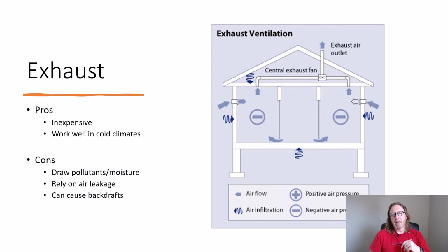Also, you have to realize stack effect naturally moves air in this same manner. So even if this exhaust wasn't working, the stack effect would pull air from the crawl space to the living space and out of the attic on a natural flow of air, which is called the stack effect. All right, so this is how most people ventilate.